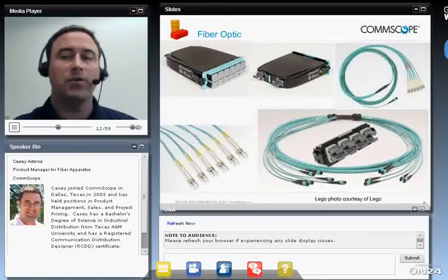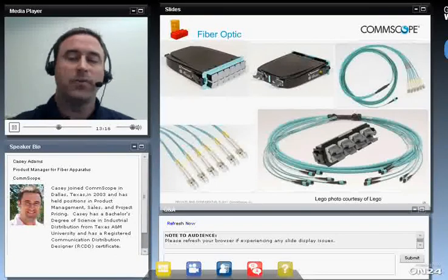On the right side, you have an MPO to LC fan-out cable. This is another form of the MPO modules and jumpers that allows for direct connect to equipment, but brings it back to a consolidation point on your trunk or backbone cable. The bottom right image shows a 72 fiber MPO to MPO trunk cable.